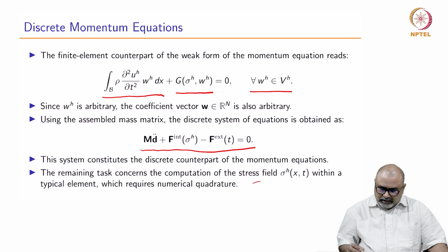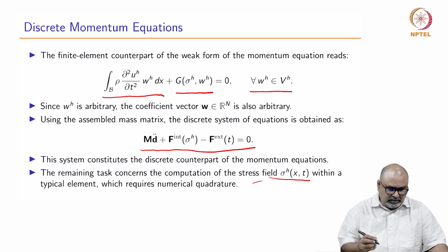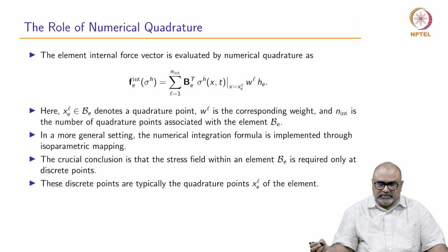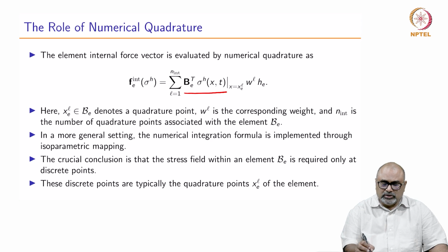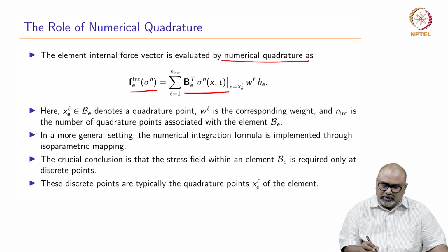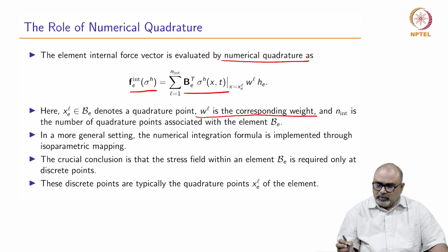Now, one can calculate the stress field within a typical element using the strain displacement matrix and the distribution of stress, and the internal force can be calculated using numerical quadrature as summation over the quadrature points of B transpose sigma^h w_l, where x_l belonging to the element denotes a quadrature point, and w_l is its corresponding weight.